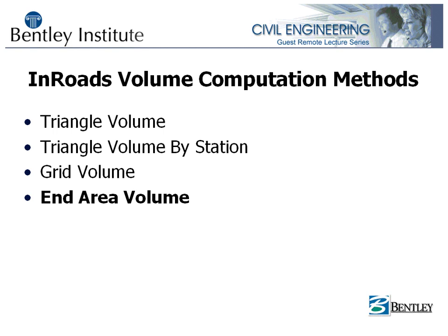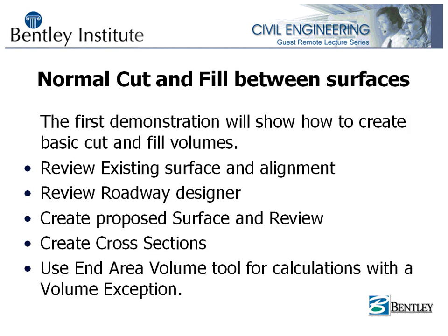At this point, let's create some real basic cut and fill earthwork volumes. We've already got some information set up for an example. This information consists of an existing surface and an ALG file with proposed horizontal and vertical alignments in it. I also have set up the roadway designer with template drops along one of my horizontal and vertical alignments.